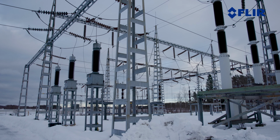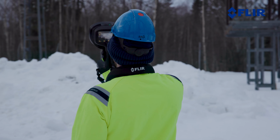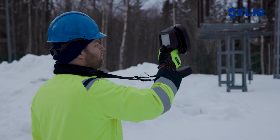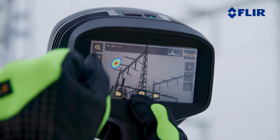With its improved sensitivity, the new SI2PD is able to detect partial discharges from up to 4 times further away than with previous generation acoustic imagers, with distances reaching up to 200 meters. For the most accurate results, we recommend a distance of 20 meters or less.